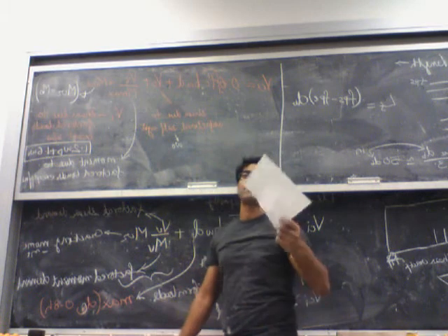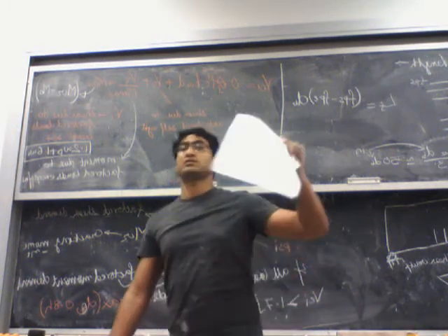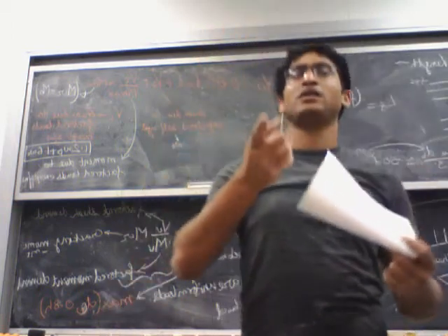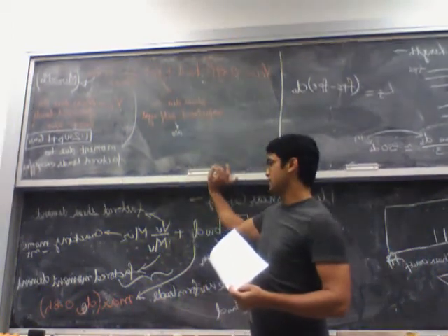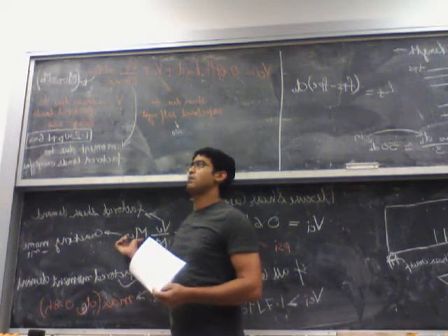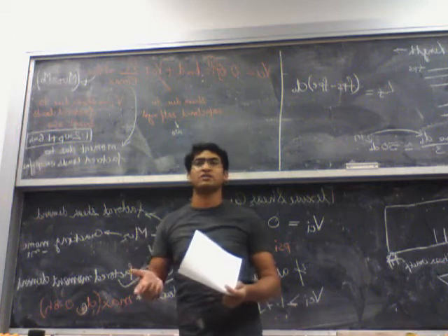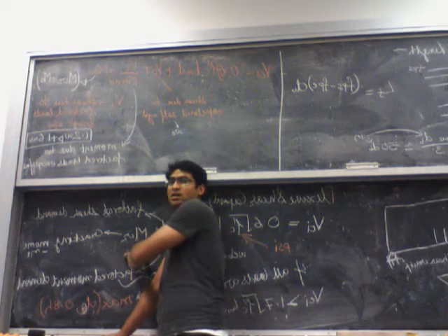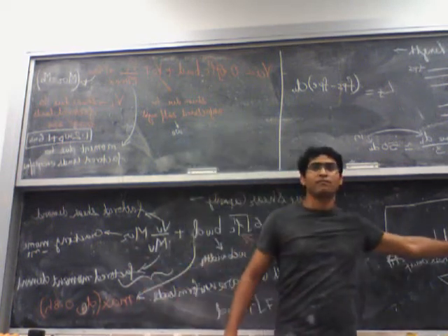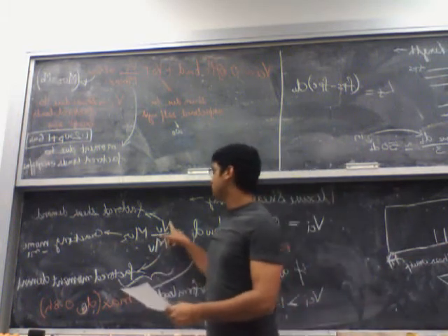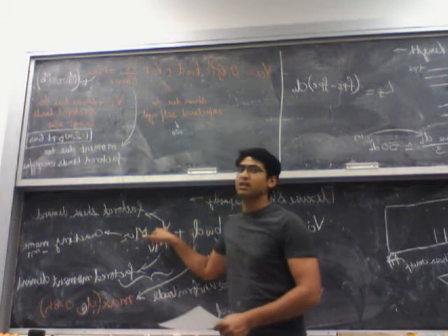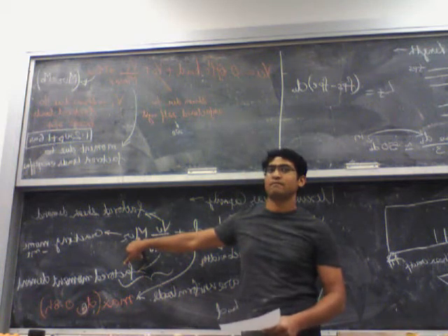So you rate the flexure shear capacity. It's labeled flexure shear capacity, but it depends on the demand, because what you are trying to do is this: Mcr is the moment which corresponds to the first flexure crack, right? So if I apply a load which produces a moment of Mcr, you'll get this flexure crack. By multiplying it by this ratio, you are trying to find the corresponding shear which will create that crack. Make sense?